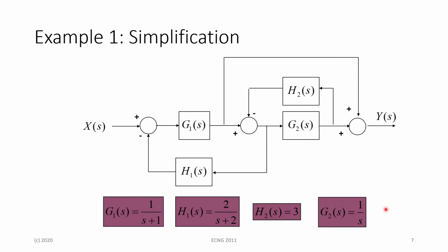So the first strategy that we are going to observe, combined with the techniques we just saw, is that when you're reducing block diagrams, the trick is to try and get rid of all these summation junctions. In getting rid of these summation junctions, we're trying to make these into feedback systems, either negative feedback systems or positive feedback systems. And once you have those, as we saw in yesterday's lecture, we can just reduce the summation junction and the G and H blocks into one full block, which we're going to see in today's lecture for our simplification process.